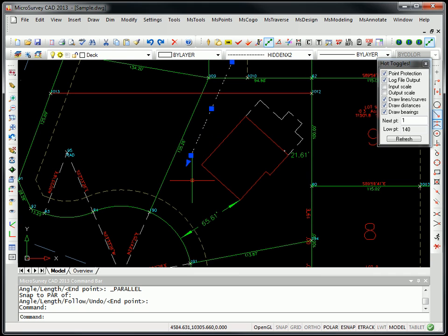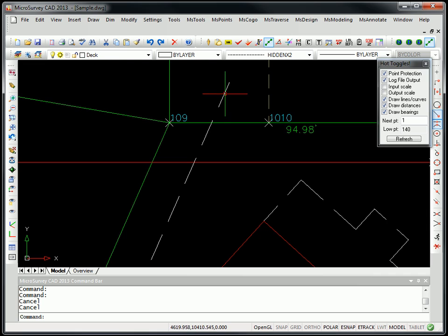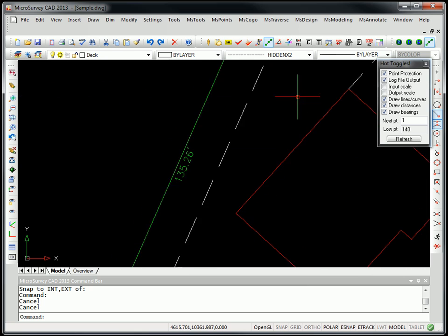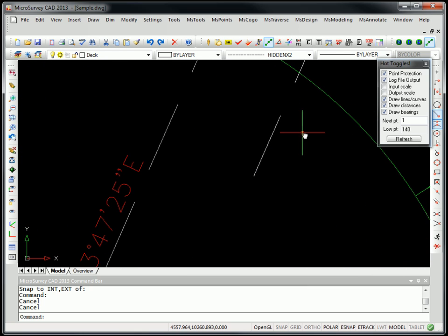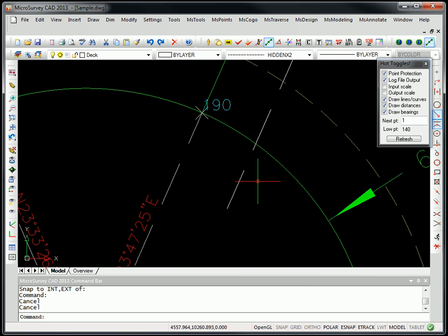When you click on lines and arcs, you'll see these lines on the end here that basically just let you quickly extend or shorten lines. Some of the other things you can do with that, if you click on it, you can also, instead of trimming a line or extending a line, you can just snap and just use an intersection snap. I can do the same thing here.